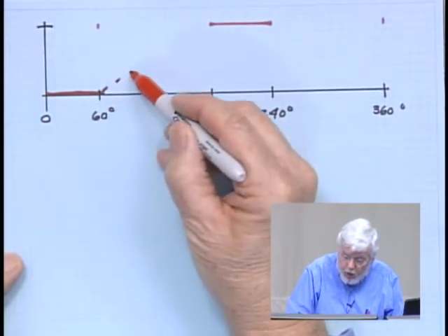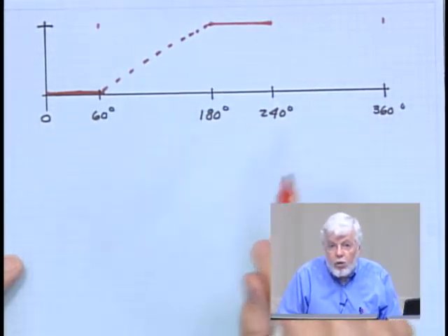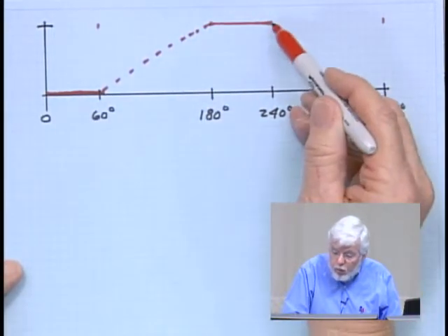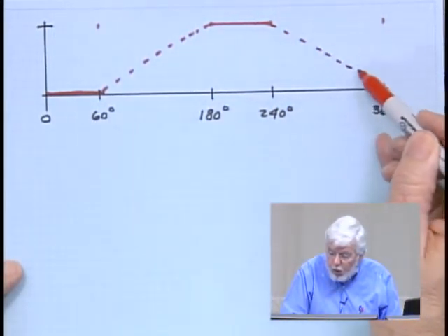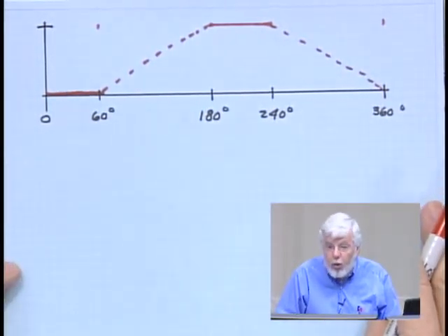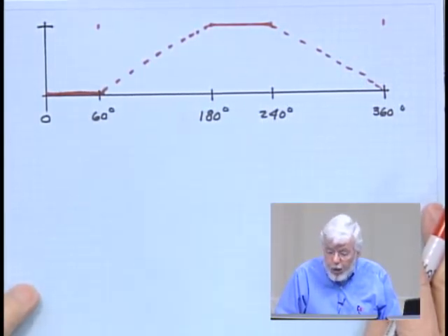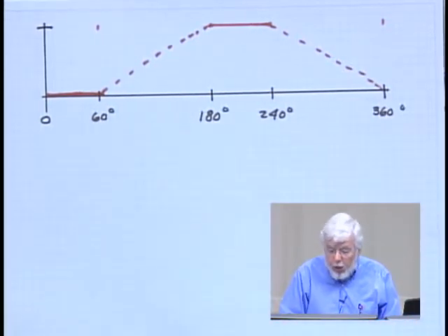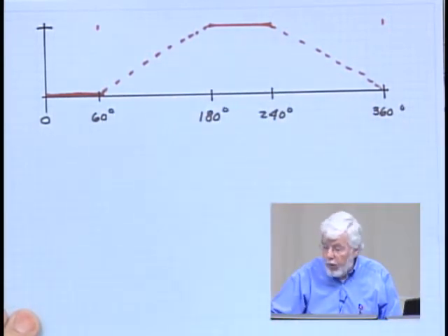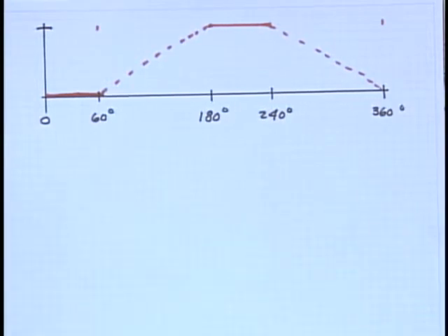And we want to get from here to there with some kind of a rise function. And that's the first challenge to an engineer in designing a cam, is what mathematical function should I choose for this motion? And as you've been probably talking about in your lectures on cams in the course, that choice of function has a big effect on a whole host of factors, not insignificant among which are its dynamics. So we're going to move now to program DYNACAM and put in this information, and then I'll show you how to put some various mathematical functions in that cam.